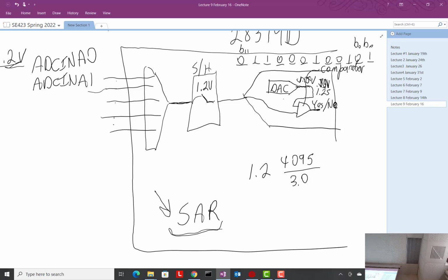So we're going to set up a PWM again. Now this PWM isn't going to drive anything in the world. All it's going to be used for is a timer, and it's going to trigger the ADC to start. We'll talk in just a minute about triggering these start of conversions. All this PWM timer is going to do, we're going to start out with 1 millisecond. Whenever 1 millisecond goes by, we can set up the PWM to say, hey ADC, start conversion.